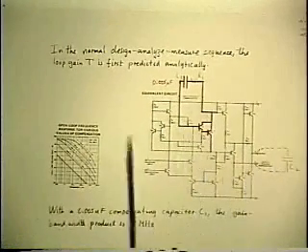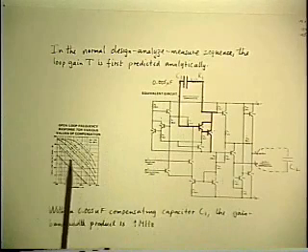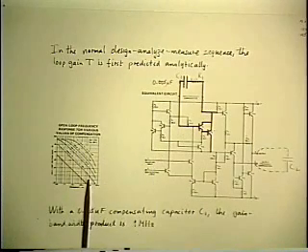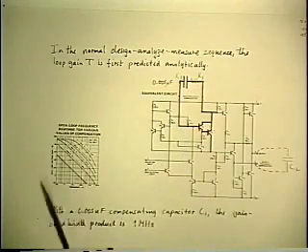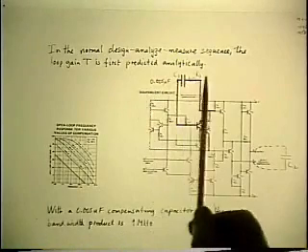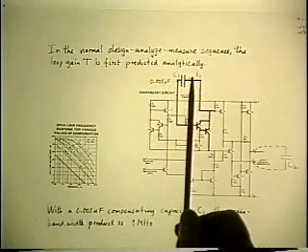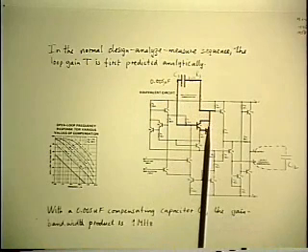Now, in this circuit, remember I changed the values from the first one, and I went back to the 5,000 picofarads that was corresponding to this lowest asymptote in here. But once again, on purpose, I left out the series resistor. So once again, I get the right half plane 0.